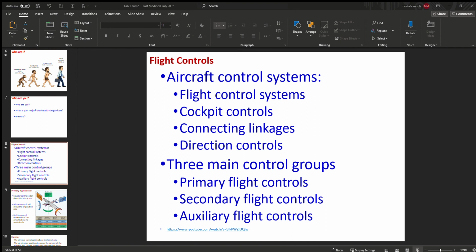Ailerons, okay, and they move in the opposite direction. The main important part here is that they move in the opposite direction of each other, which was not the case for the different sides of the elevator. The elevator is at the two different sides of the tail, but these two sides essentially serve as one side, and they are connected to each other. So they go up, they go down together.